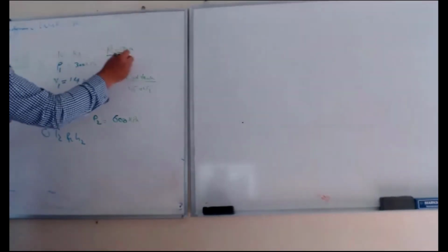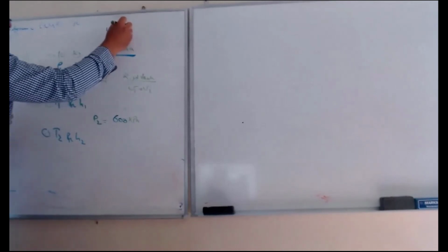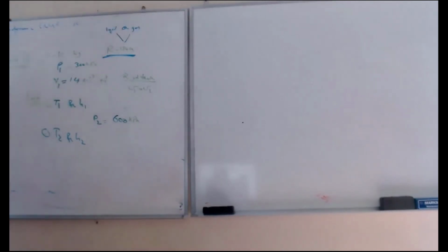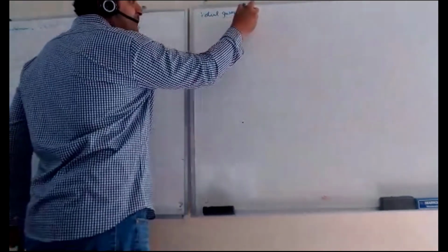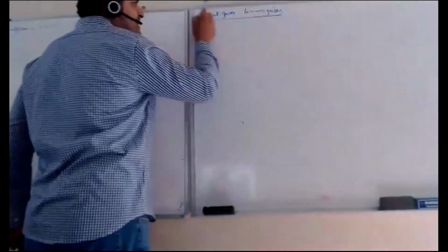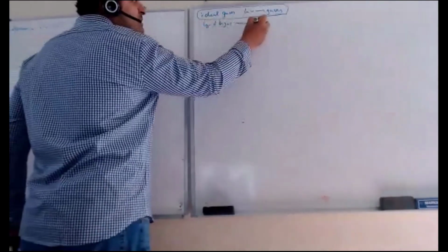But this is a fluid which has liquid and gas, which means a mixture. If this were pure gas, you can use the ideal gas law. The ideal gas law is something we use only for gases, please do not mix. But if you have liquid and gas, like a mixture, use steam tables.